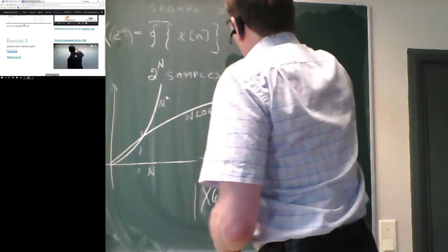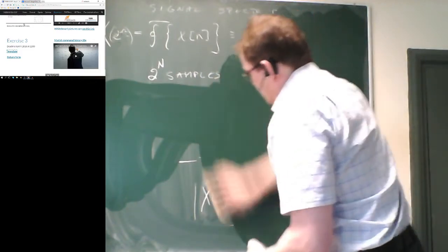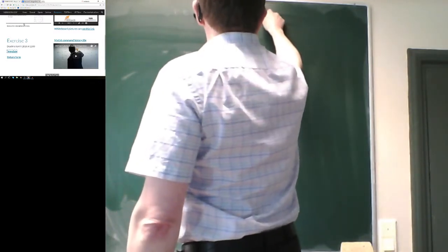However, the fast Fourier transform calculates the spectrum only for 2 to the n samples. And sometimes we are more interested in how the signal is changing by time, meaning what kind of spectral components the signal has over time, and then we are talking about a spectrogram.